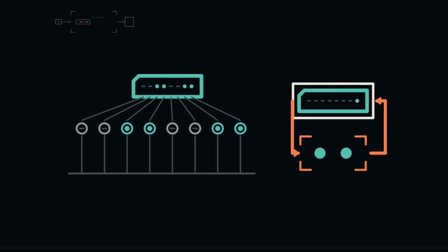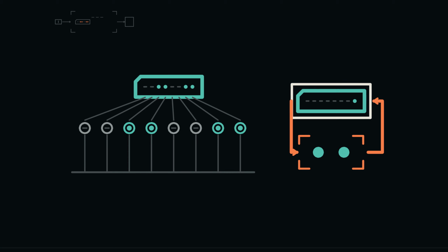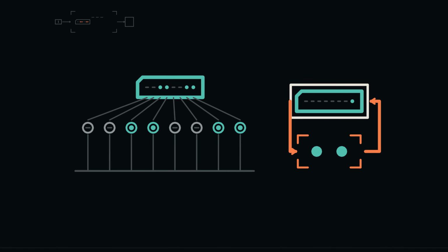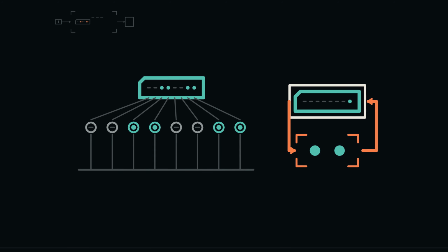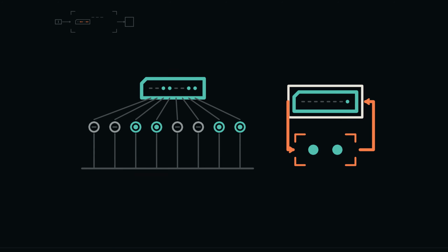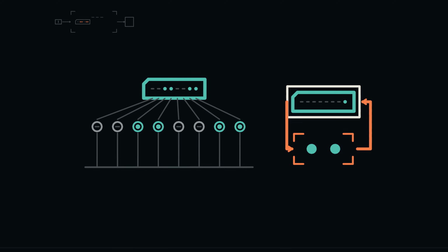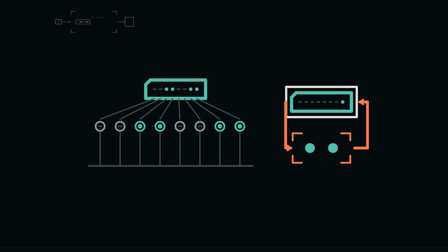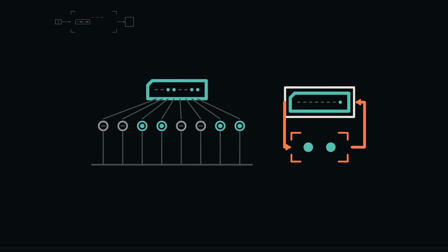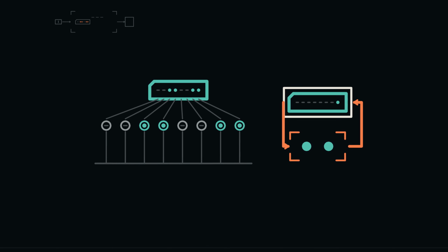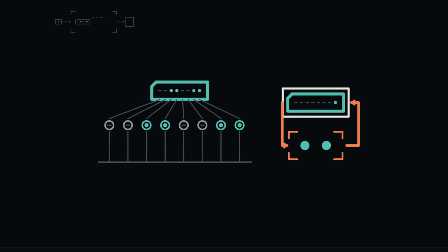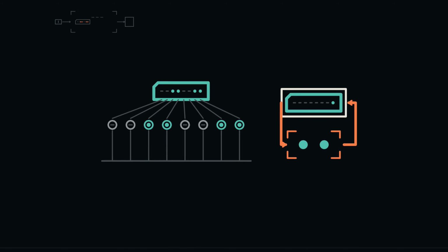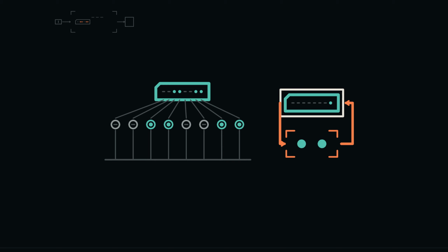Begin with all zeros. The first enabled edge captures a pattern ending in 1. At the second, that trailing one returns to 0 and the position left of it becomes 1, giving the ending 1, 0. The third ends 1, 1. The fourth turns both trailing ones to 0 and advances the next position, giving 1, 0, 0. These proposals form between edges and are then captured. Their carry steps never become stored intermediate states.